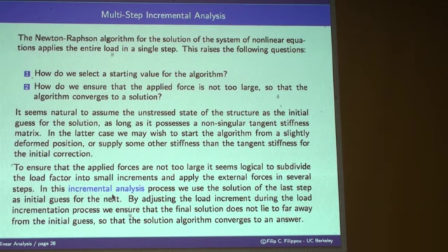It is not wise with a nonlinear structural response to run any kind of automatic solution without load factor control. Now, in OpenSees, load factor control is understood as displacement control.